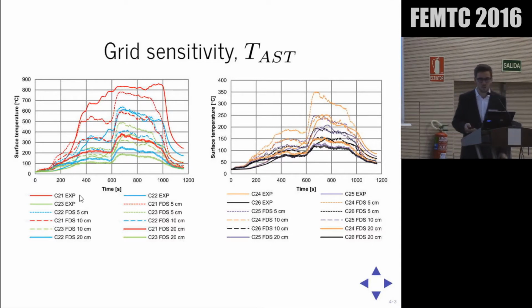That makes sense, bearing in mind what I talked about before, that the temperatures retrieved from thermometers are only an approximation of the adiabatic surface temperature. The thermal inertia of the steel plate and the heat loss through the insulation padding are factors that mean the thermometer temperatures become lower than the adiabatic surface temperature.